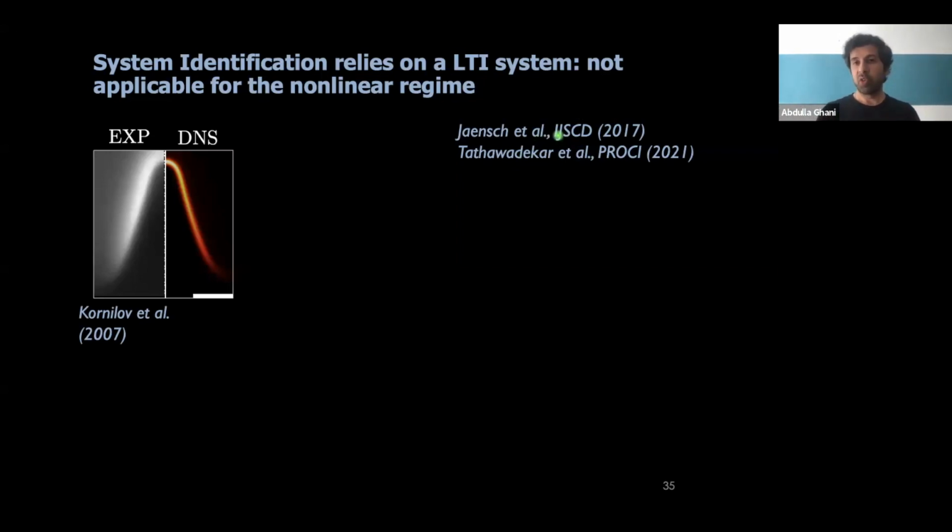So what they have shown also in a follow-up paper in 2021 was that it is possible to reproduce the nonlinear flame response with one single computation, but the length of this computation is super long. So for this simple laminar flame here, the computational time, DNS is referring here to flame resolved DNS, so the chemistry is still simplified, which is kind of a typical thing we do in thermoacoustics. So the computational time here was 1 second, which is, you do it just once. You cannot do that in a design phase or for a turbulent flame, because then you would need more than 1 second even.